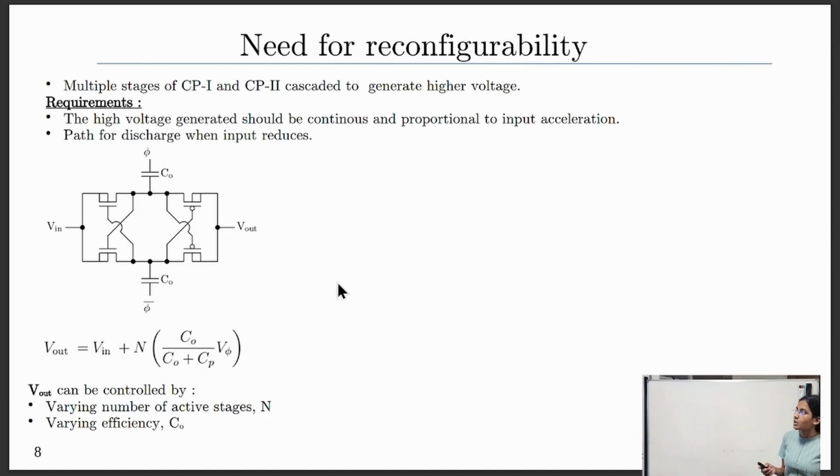One thing: when the clock is not applied, Vout will charge up to Vin through leakage current. So let's say we have cascaded the required number of stages and we need the minimum voltage. Then one of the charge stages is active and the others are all inactive.